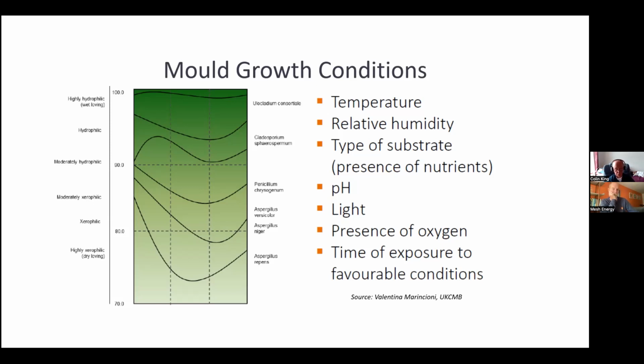So what you're looking at is things like vapor open material, like Pavatex, Pavadenso, some of these insulated lime plasters, which allow the free flow of water in the form of vapor through the structure in both directions. Because what you're trying to do is actually mimic the original vapor strategy for that structure, even though they didn't think about it in those times. They used the materials they had.